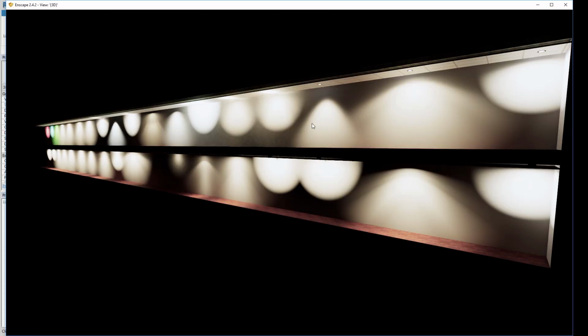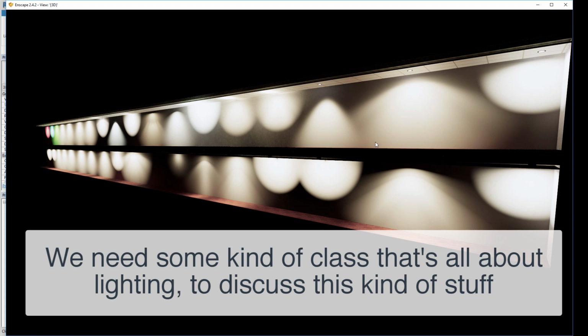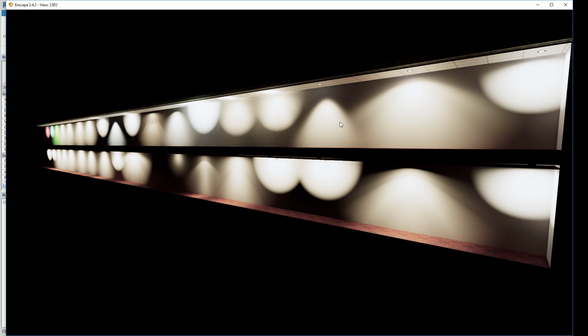So this is the IES gallery that I have posted to Canvas, and what you'll see pretty clearly is that there are a lot of light fixtures out there, and they are all kind of using Revit's internal IES file connection. And the light output that you get from these is quite different. More of a cone shape here. This would be more typical of a downlight. This one is a little wider field of distribution. And then here, this one is very much a wall washer.